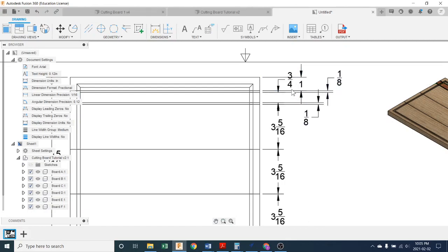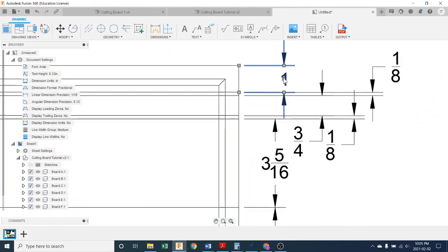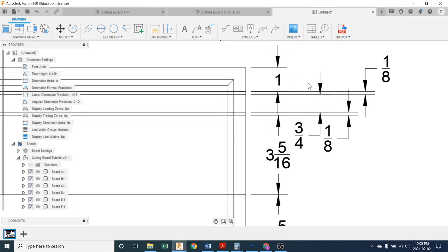All right, that is still pretty messy. And I think if I pull this one out like this, and then I drop this dimension down by dragging it, and then I could bring this 1 inch back in. I'll put this one right in line with these ones. Whenever you can line up the dimensions, it's better. It looks neater and tidier. And if they won't line up, you zoom in a bit, and then it starts moving a little more precisely.